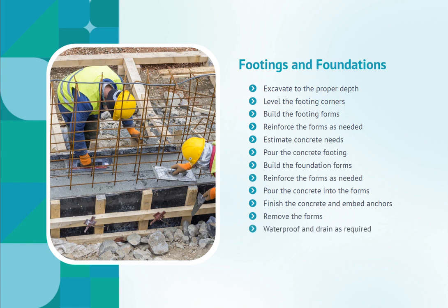Build the foundation forms. Reinforce the forms as needed. Pour the concrete into the forms. Finish the concrete and embed anchors. Remove the forms. Waterproof and drain as required.